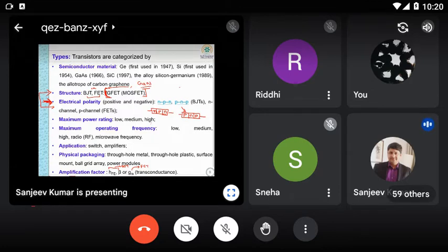And HFE means this is a hybrid parameter, the same thing, because when you are taking the equivalent circuit diagram of a transistor, if I'm using the hybrid model, H is referred based upon that. F means forward. You can see E for emitter. So that beta and HFE both are same.